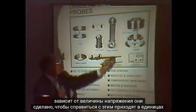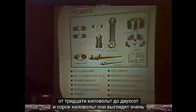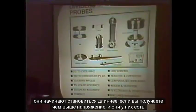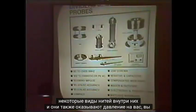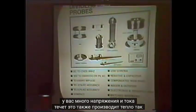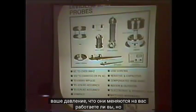These come in units between 30 kilovolts and 240 kilovolts. They look very similar to the one you see there, except they start getting longer as you get to higher voltage. And they have certain kinds of filaments inside them, and they're also pressured up. You notice the pressure gauge here, and when you've got a lot of voltage and current flowing, it also produces some heat, so your pressure may change on you while you're working it.